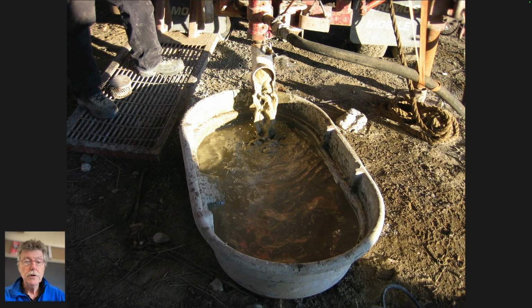All right. So the drill pipe goes into the ground here. This is just a 90-degree bend like you'd have in your house. So it goes down, but it has a side exit that comes here. So the drill fluid goes in here into the top of the drill as it's going down. It travels down the center of the pipe to the shoe, keeps it lubricated, washes the cuttings up back around the outside of that pipe, and then when it gets to the top, it comes out here. So this is the exiting fluid, which is carrying with it the cuttings.